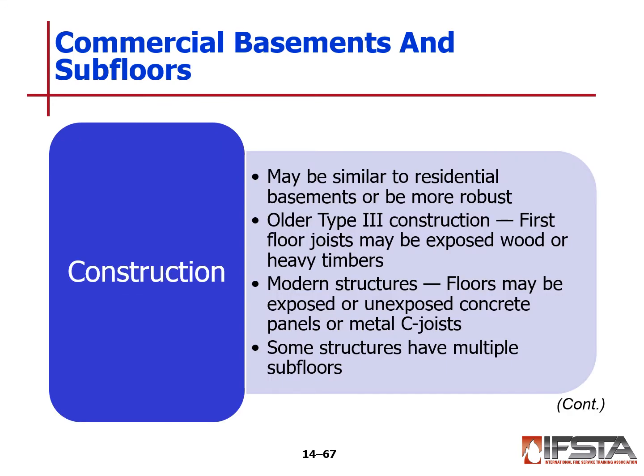Commercial basements and subfloors. The construction may be similar to residential basements, or it could be more robust, such as concrete. In older Type 3 construction, your first floor joists may be exposed wood or even made of heavy timber. In modern structures, the floor may be exposed or unexposed concrete panel or a metal C-type joist. Some structures have multiple subfloors.